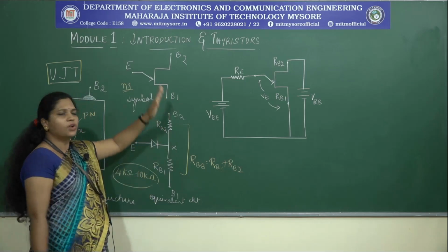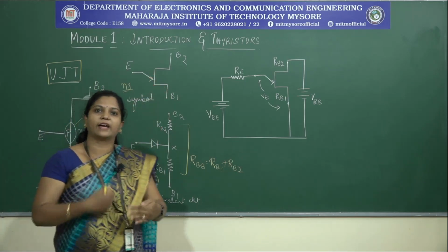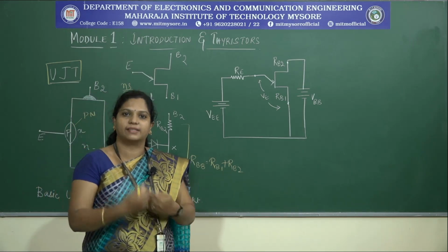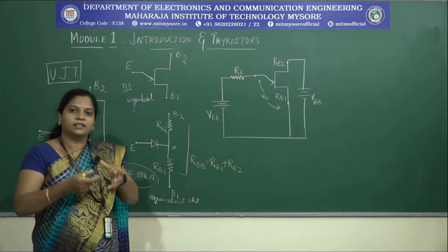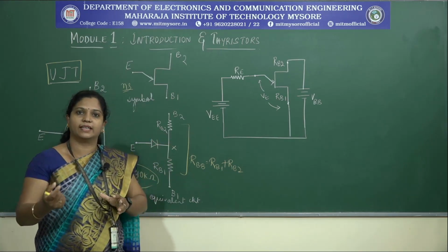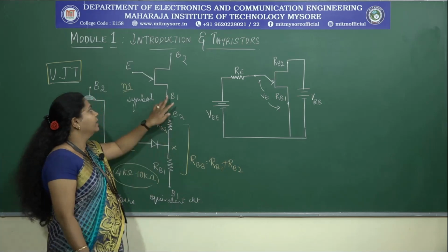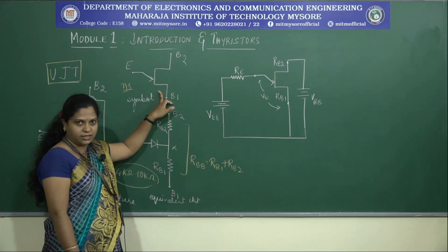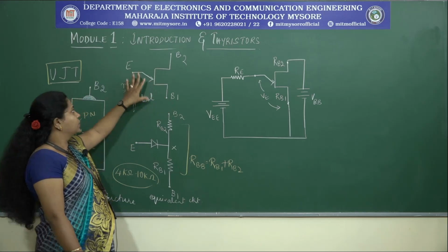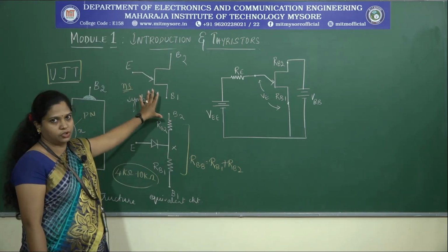So, apart from R triggering and RC triggering, if we want the switching action to be faster, or if the circuit we build for triggering an SCR is for a high speed application, then we prefer the UJT. So this UJT is used only as a switch.